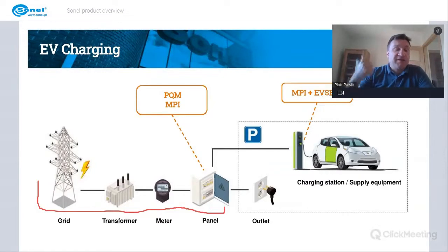So for insulation resistance, MZC series meters; for a short circuit loop, MRU meters for ground resistance, MMR micrometers for continuity, and so on. Or we can just use MPI series meters, the multifunction meter, which has all these functions embedded.